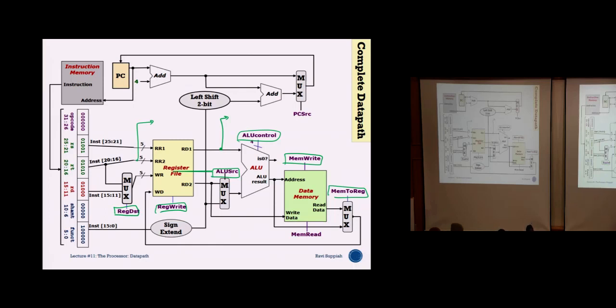Just want to clarify, with the mem, right? When you exercise the mem, it just reads the data. Memwrite is to update the data memory. It uses the address because you update some memory location, correct? So the address tells you the memory location, then the data tells you the data. Then the memwrite is the pin to trigger the memory write.